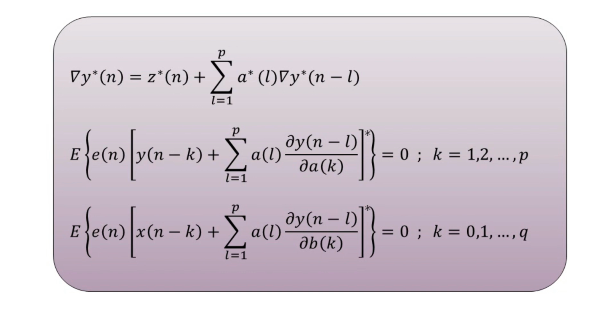Now after looking at these two equations, we observe the non-linearity here. Because of the non-linearity, it is quite difficult to find the solution at the optimum filter coefficient levels. Therefore these two equations are not generally solved directly, whereas the steepest descent methodology can be opted for, searching out the solution in an iterative fashion, which will be a local rather than a global minimum.